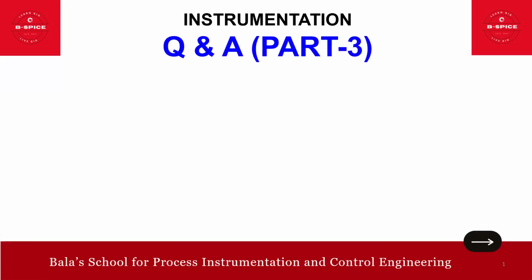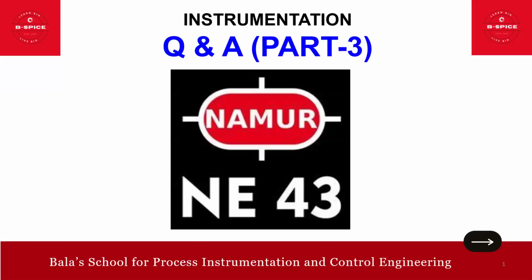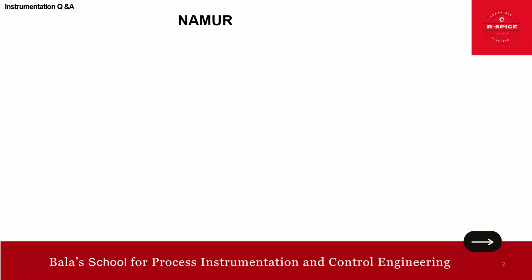In this session, we'll continue with instrumentation question and answers part 3, wherein we'll focus on NAMUR. There are many standards that come under NAMUR. NE43 is the most famous one. We will see all the NE related standards, predominantly focusing on 43, and the remaining ones we'll also cover. So let's move on.